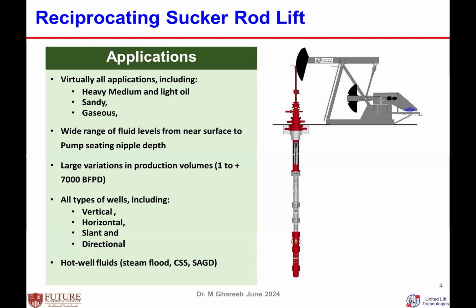Is all the background about this system, that it's used only for shallow wells, or with no gas, still true? It has changed. Currently, this type of artificial lift can also be used for what we call unloading, or deliquefying and dewatering gas wells. That means yes, it can be used with a very high amount of gas. But let us see how we can use this pump for high gas ratio wells, for sandy wells, and so on. Even for pressures, this system doesn't care about bottom hole flowing pressure.